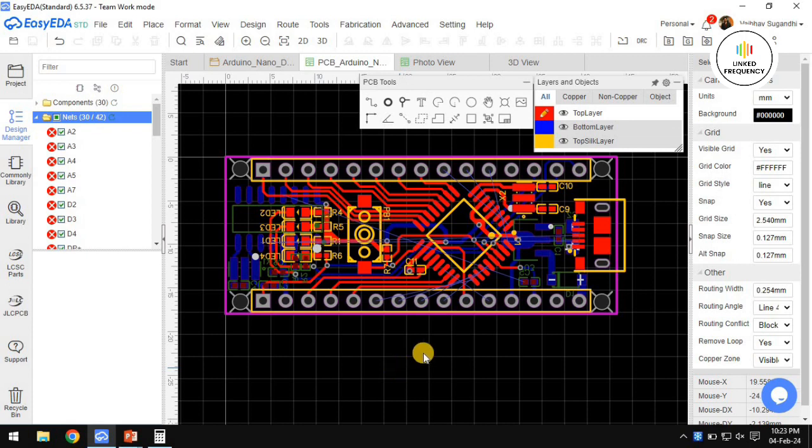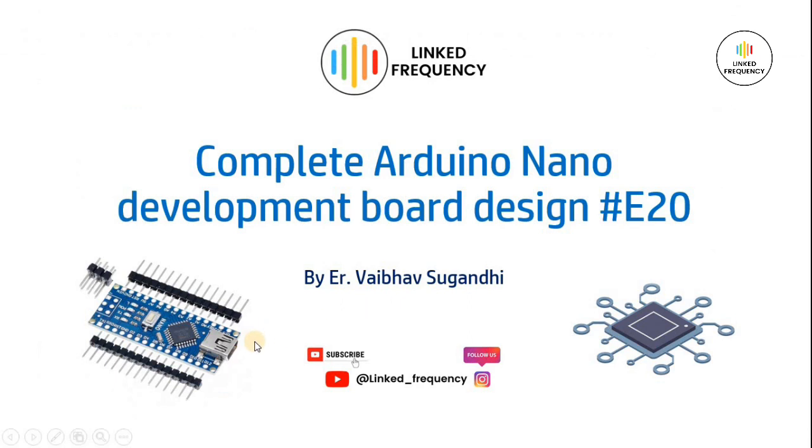When I started placing these components, I thought of aesthetics and I thought of copying the existing module directly, but still I have not copied it completely, as I mentioned in the beginning part of this video. I have changed this header and I placed the USB to UART converter at that place, and these connectors also, where there is a RxD, TXD, ground, V in, ground, and opposite to that there is a RxD, TXD.